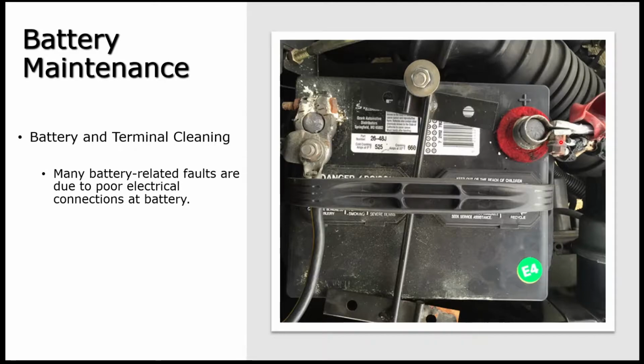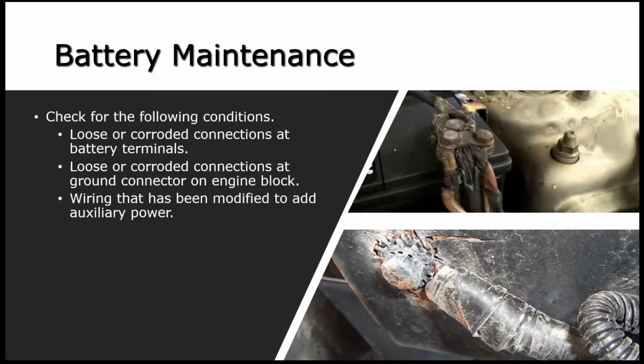So we're dealing with battery terminals that need to be replaced, corrosion that needs to be cleaned, all that kind of stuff. Things that we need to keep our eye out for. And we're going to talk about how that happens here in a minute. So looking at the battery maintenance side of things, if I look here, it's totally unacceptable, whether it be ground or positive, to have this type of scenario where battery cables are put into play.